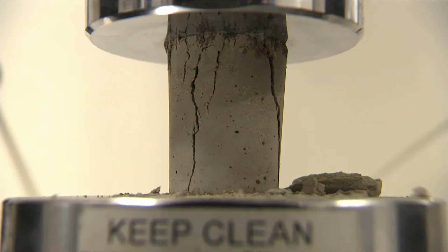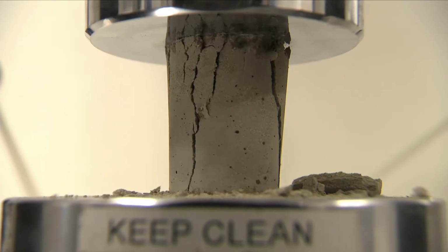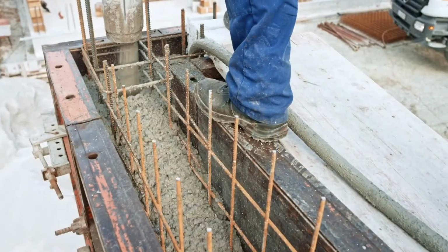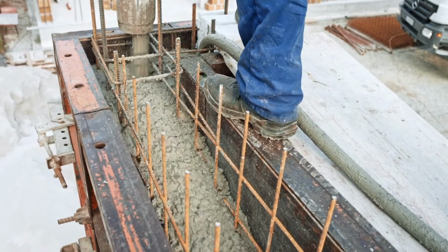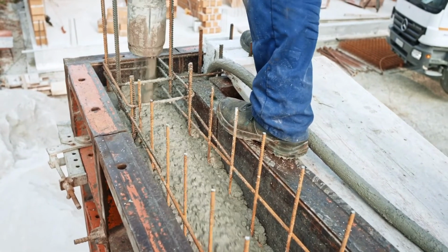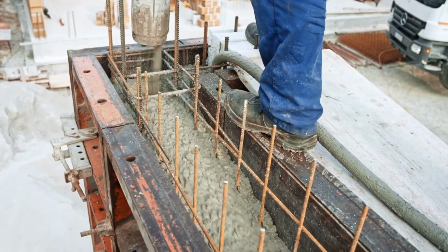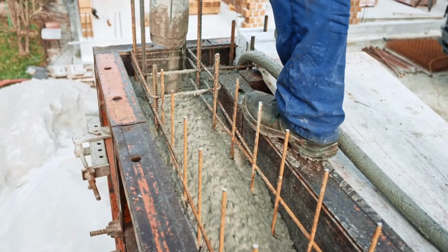There are well-established procedures for taking concrete samples, preparing test specimens, storing them on site, transporting them to a laboratory, and finally testing them in a compression testing machine or other apparatus. Concrete rarely tests well when testing protocols aren't followed. If test results constantly show lower strength, then the only way to overcome that is to increase overdesign, which generally raises cementitious material content.